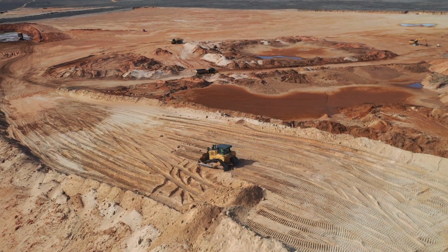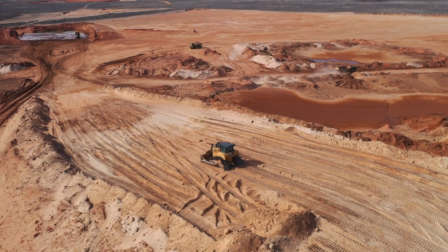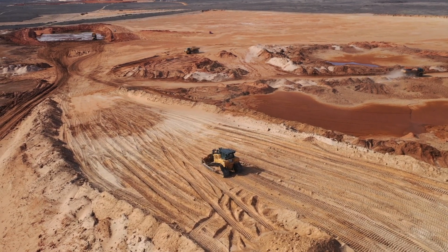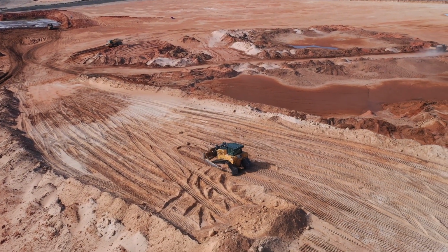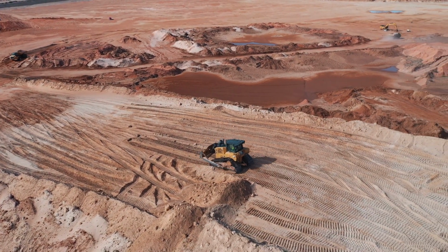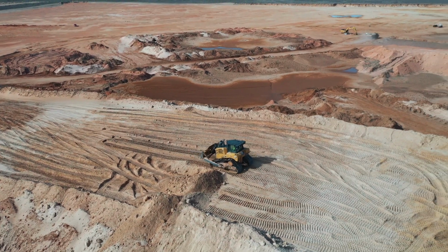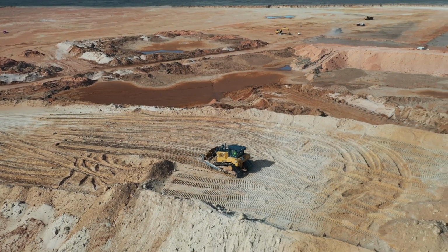When dozing or trimming down a grade or pushing to a bank or edge, place the dozer in a face-down direction with the dozer blade. Never place the dozer sideways to the slope or bank. Operate straight up and down slopes whenever possible. Sidehill operation reduces stability, which could cause machine rollover. Never reverse towards the edge of a steep bank.